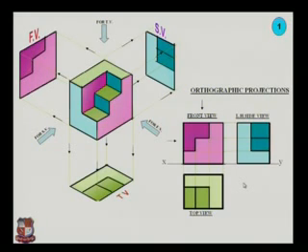From the intersection point, the lines will be extended vertically upward, so that by the combination of the projectors of the top view and front view, we can get the side view above the XY line. So it is the first figure to draw the orthographic projections.